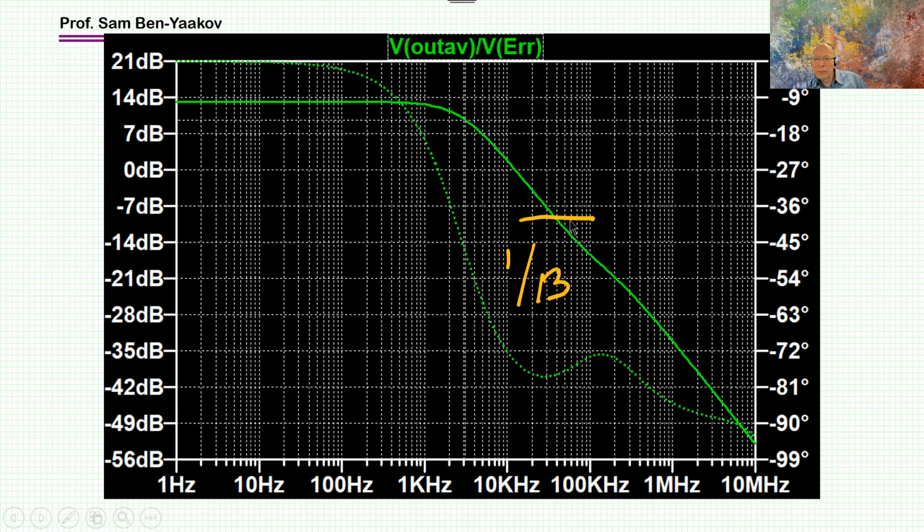This will be a type 2 compensator because it's straight here. And the phase here is 80, so that the phase margin is something like, I don't know, say 90 degrees or even more than that. That's very good. Excellent. Actually, we could have closed the loop a little bit further, but I have to worry about the switching frequency.